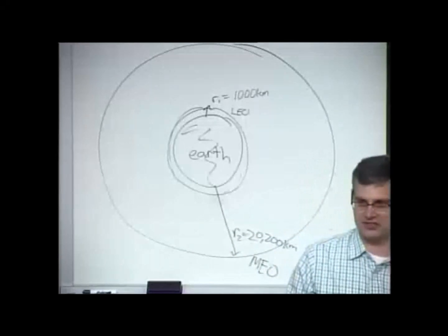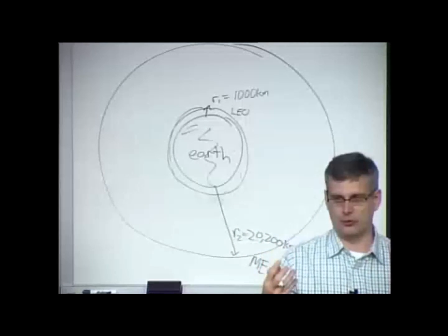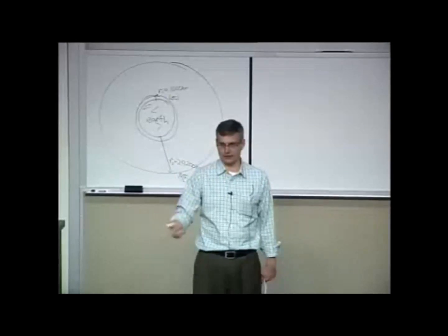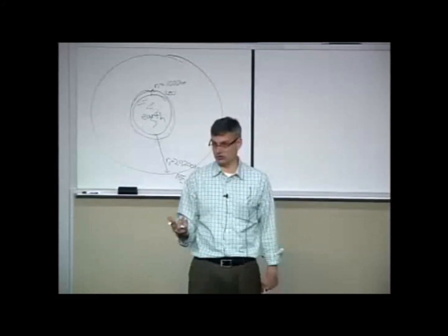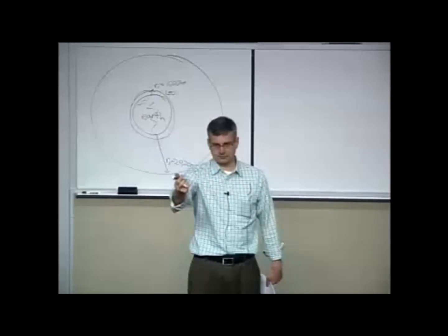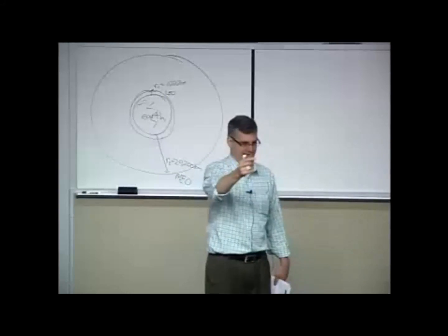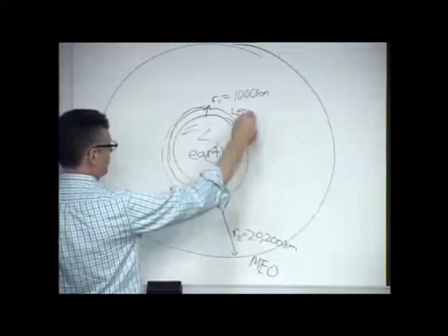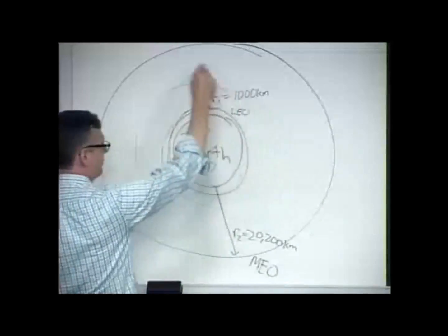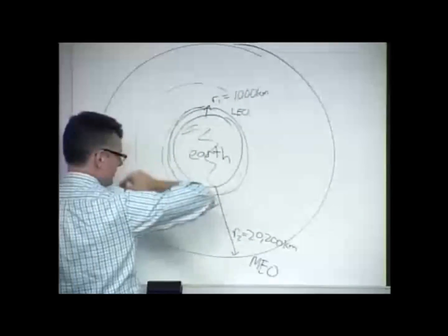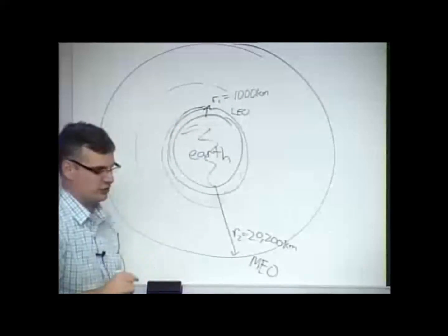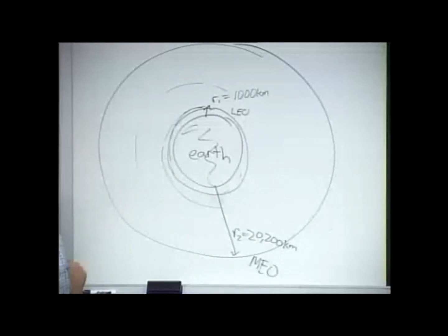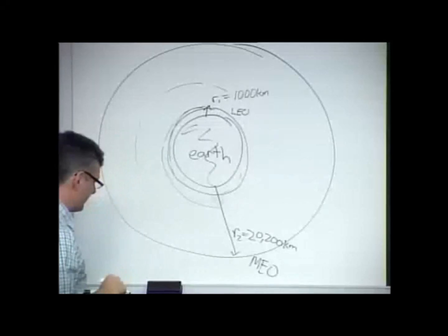We've actually had some launches with a small, low-powered ion drive that provides very little force but can do so continuously for a very long amount of time, with relatively little fuel weight. In that case, you slowly, over the course of days, spiral up until you get into medium Earth orbit, in which case the ion drive shuts off and disengages. And voila, there you are, in medium Earth orbit for the rest of the satellite's useful time.